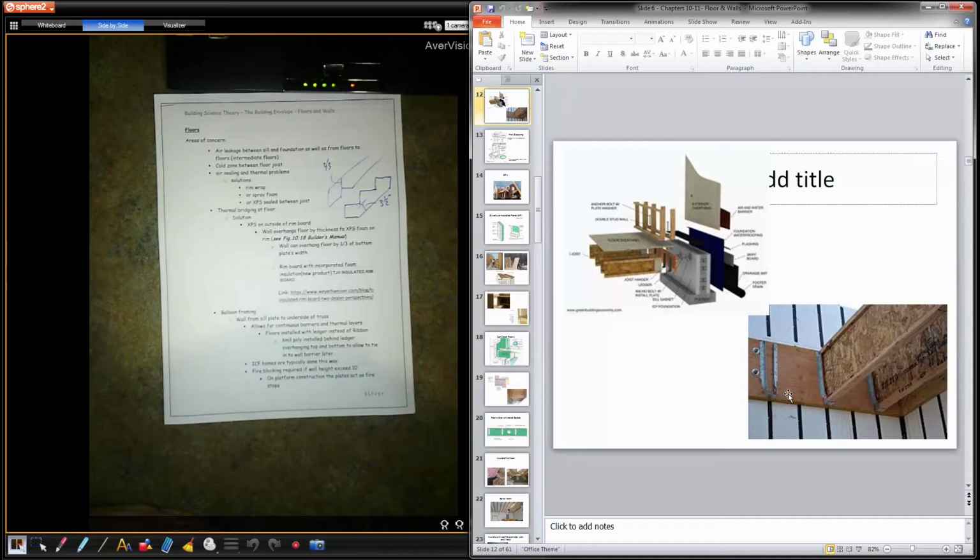So that's a pretty good system. And you can see right here, there's your ICF foam. There's brackets there. The ledger gets bolted onto that, so it's thermally broken, right? We have a piece of continuous insulation on the inside, a piece of continuous insulation on the outside. The floor goes into that. So it seems like it's weaker, right?